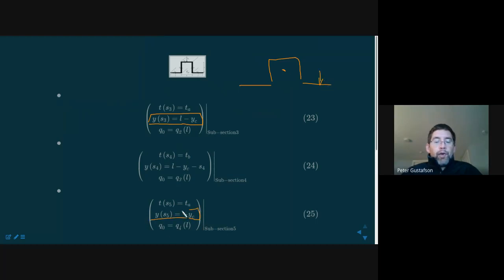So those, we need to be very careful with these geometric descriptions of the positions within the cross section. They're not always going to be this easy. In some of the homework, they'll be a little bit more complex, but always come up with a way of defining where your centroid is. You can then define any number of other coordinate systems you like in order to find a convenient way to write your distance, x or y position relative to that coordinate system. And I hope now this is clear.